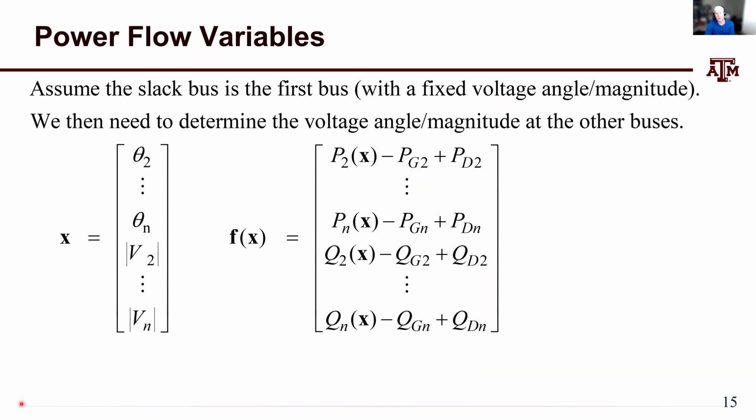Okay, so this is a power flow formulation in polar form. We're solving for the angles at the buses and the voltage magnitudes at the buses. Sometimes, of course, the voltage magnitudes are fixed because you've got a PV bus, and your set of equations is the power balance equations: real power balance and reactive power balance at the non-PV buses. And at the PV buses, oftentimes we just replace the Q equation by an equation that says the voltage magnitude is equal to the set value.